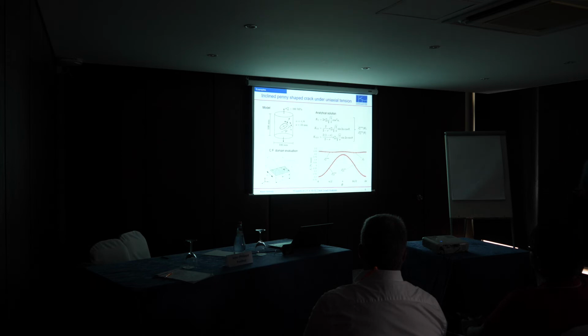But we did all this to perform three-dimensional analysis, so I will also show a three-dimensional example. This is an inclined penny-shaped crack under uniaxial tension. This load leads to a continuously changing loading along a three-dimensional crack front.